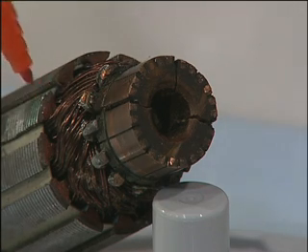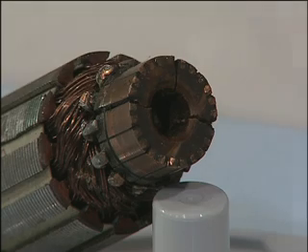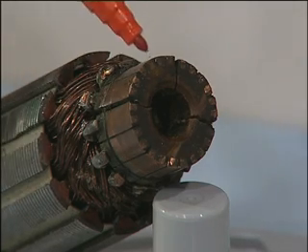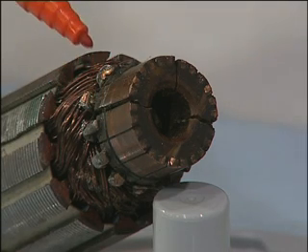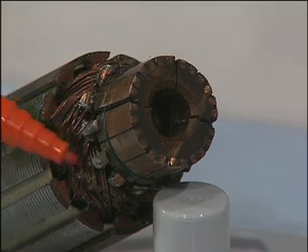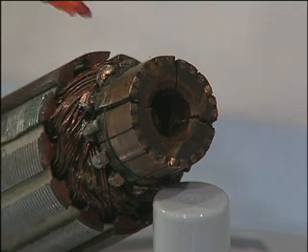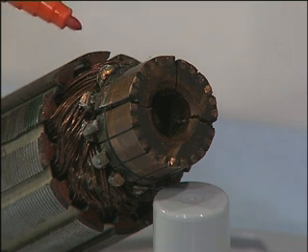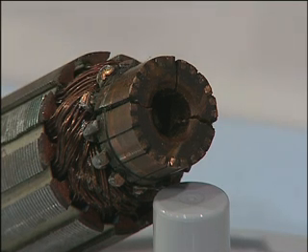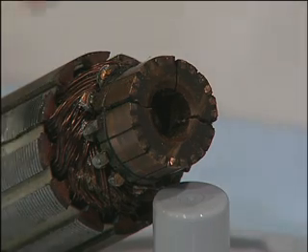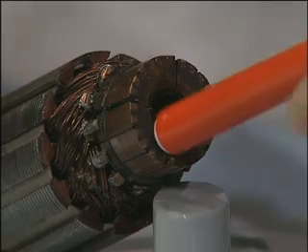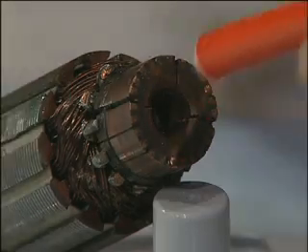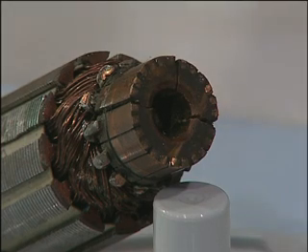So, the coils here are coming from the 12 slots on the rotor, and you have the commutator segments. The coils are soldered onto the commutator segments here. If you notice, the coils are soldered in the winding fashion that we just discussed. This type of winding fashion is called the lap winding. Now, this whole rotor will be mounted onto a central shaft, and above that there will be another enclosure called the stator, which will have the north and the south poles. It could have more than one set of poles, and that would make the complete machine.